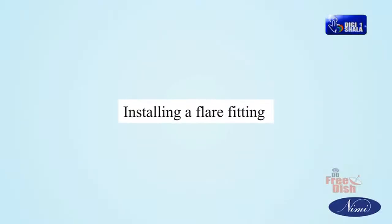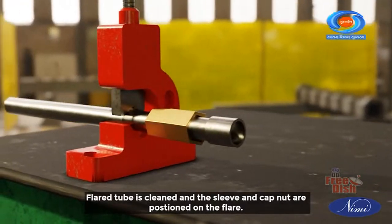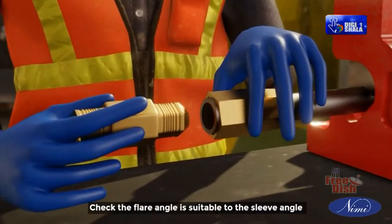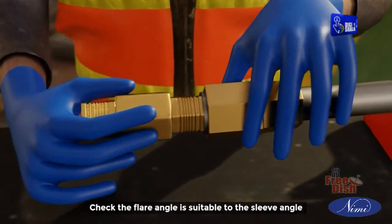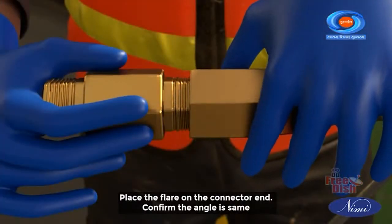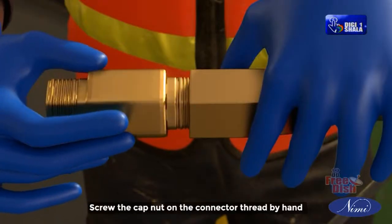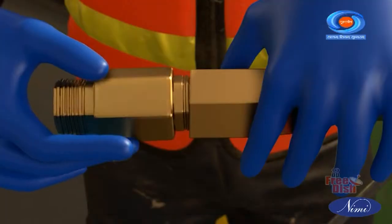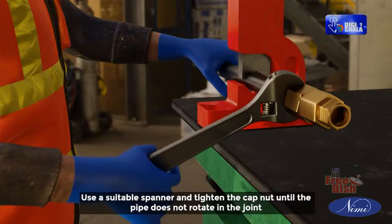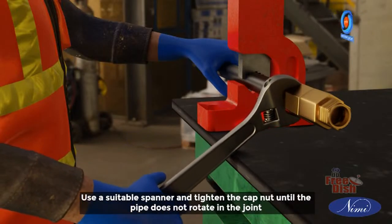Installing a flare fitting. The flared tube is cleaned and the sleeve and cap nut are positioned on the flare. Check the flare angle is suitable to the sleeve angle. Place the flare on the connector end. Confirm the angle is the same. Screw the cap nut on the connector thread by hand. Use a suitable spanner and tighten the cap nut until the pipe does not rotate in the joint.